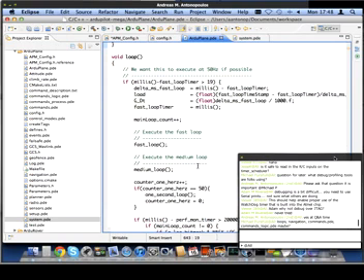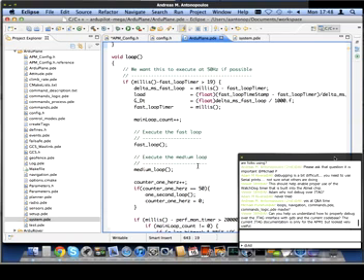We're primarily either polling or interrupt driven in ArduPlane and ArduCopter. We don't have a real-time operating system, which means there's only ever one task happening at a time. Now, in order to cope with multitasking, what we use is interrupts. So that means that the code regularly gets interrupted to do something else. For example, that 1 kilohertz interrupt that reads the gyroscope and the accelerometers on the APM1, and an approximately 100 hertz interrupt that reads the barometer on the APM2, and various other interrupts like that. Then there is the main loop, which the Arduino environment sets up to be called continuously.